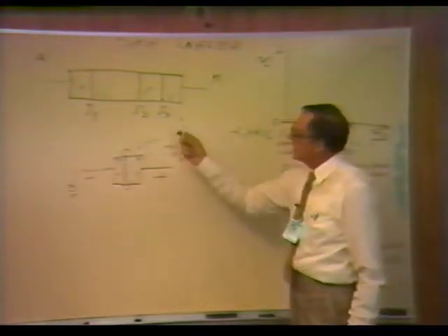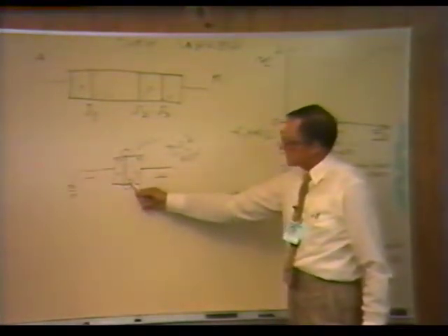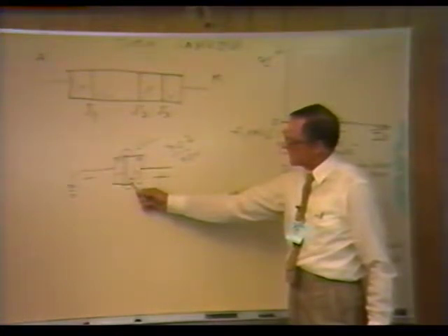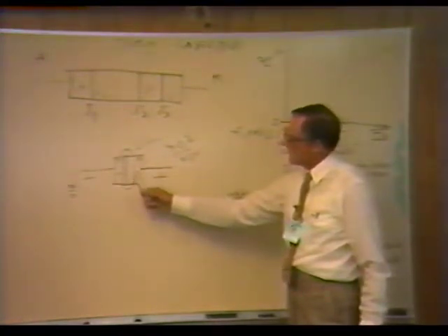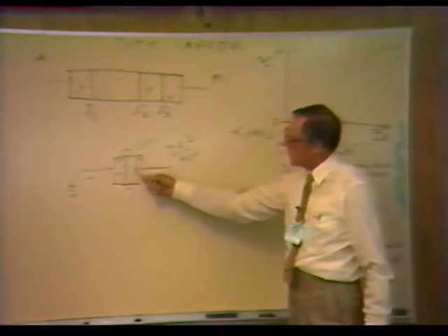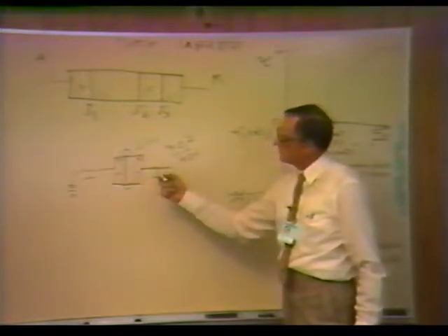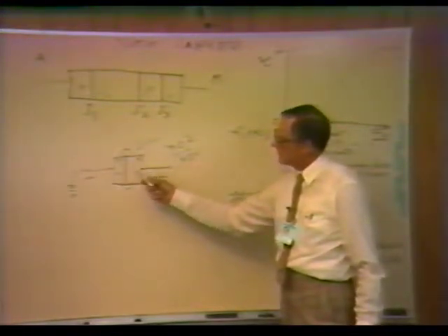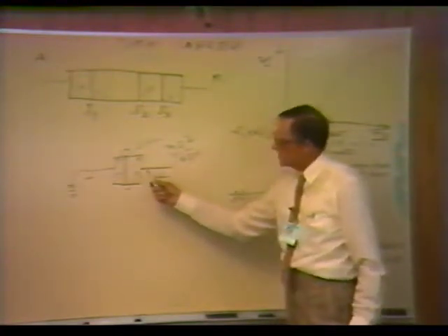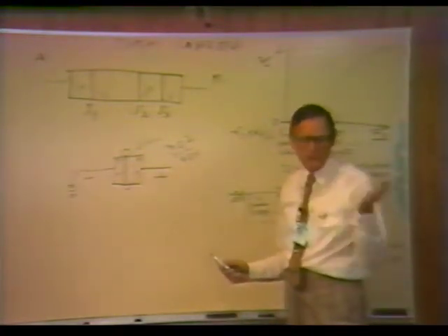That's how a junction is able to sustain the applied voltage in the reverse direction to hold off. And that's how, when you increase the voltage too high and you get the creating of electron-hole pairs, the junction breaks down and you get reverse breakdown voltage.